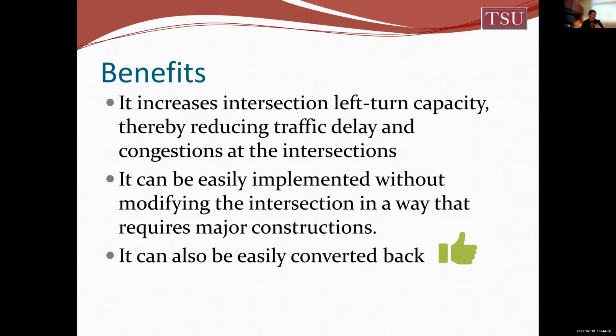The second is that it's quite easy to implement. You can see in this video, they just put signal lights in the median and then draw markings on the pavement to indicate this contraflow left lane. Then it can be used. I think it's very easy because I have been working on other innovative intersection designs like the continuous flow left turn design.